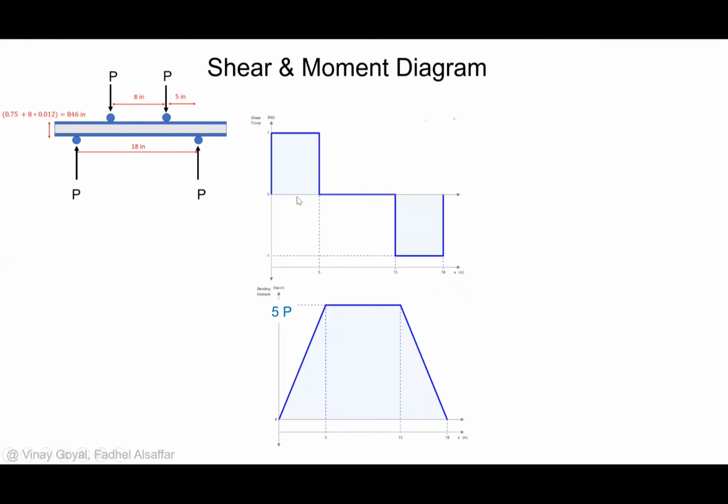The things that we'll be showing is that in this problem, the area between the two forces has zero shear stress and a constant applied moment, which will result in constant axial stress in the middle, and the shear stress is very close to 0.